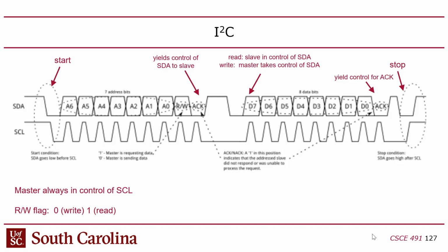So what happens is that you're supposed to put whatever data you want out on your data line, right? And just like a latch, when you want that data to be sampled by the other side of the connection, you assume it's using a latch to do so, meaning that you raise the clock up, you let the clock be high for a little bit, and then you drop it. And you assume that the aperture time, which is the time that we're reading the data, is not on the edge of the clock, but it's when the clock is high.